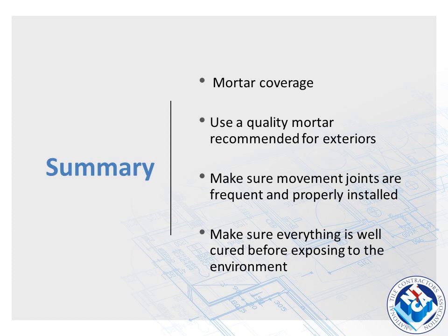Use quality mortars recommended for exteriors. Again, I personally would recommend a 2-component, one that meets ANSI A118.15.